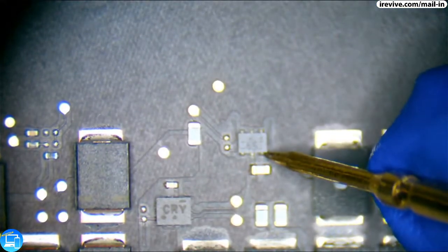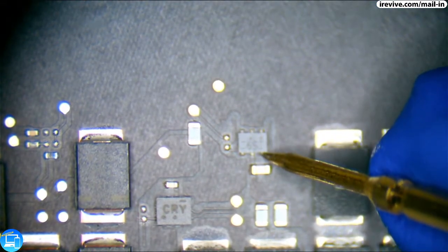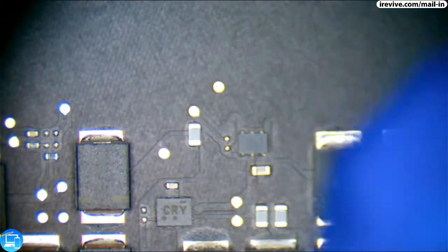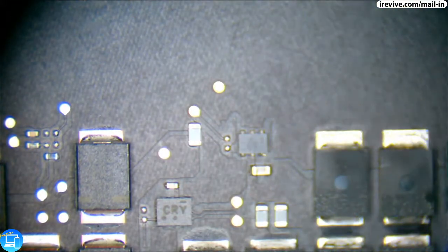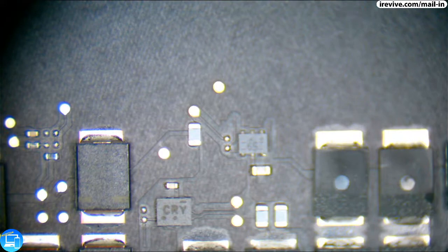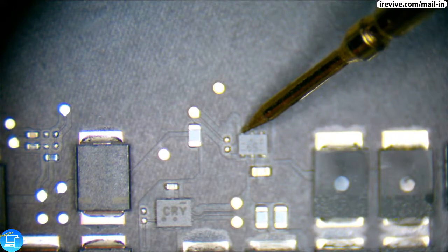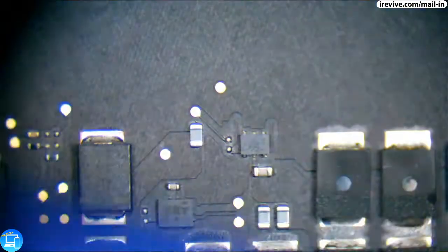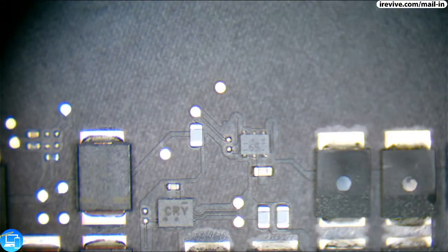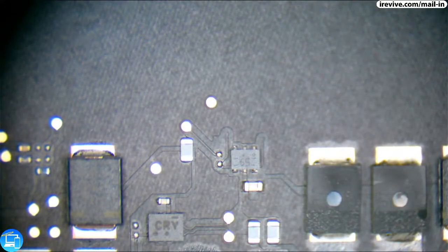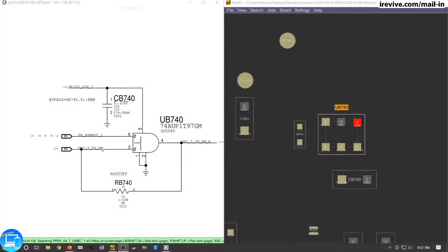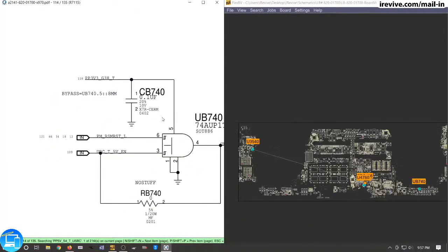And what do we have? Nothing coming there, which may be okay because PM_RSM_RESET_L is a low line, but nothing at all coming from UPC T5V enable from pin 3. All right, we're going to learn today. Where does this line come from?